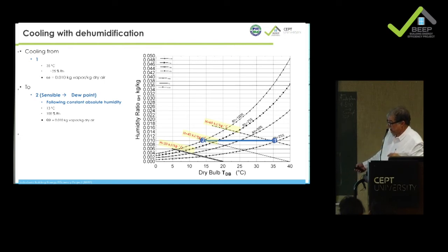And there, what is happening is that we are cooling sensibly up to, let's say, the saturation. In reality, if you go into a very cool coil, it will follow a line, not a straight line, but normally we always show it like this, up to the saturation level. That means we are cooling the air from 35 to approximately, how much is it? 13 degrees.